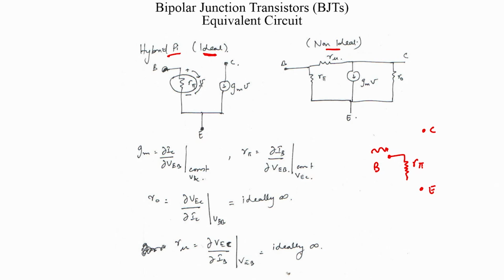If you head back to our original discussion on what constitutes a transistor, you will appreciate what that means. Your collector to emitter current is dependent on the base to emitter voltage. Let us say that is your VBE. This is going to depend linearly on the base to emitter voltage, provided we have linearized the circuit,